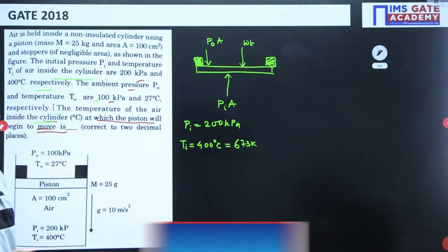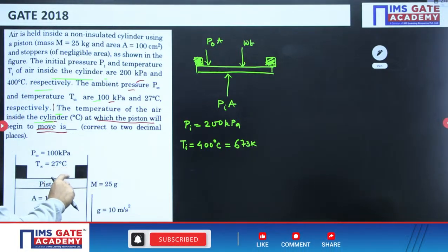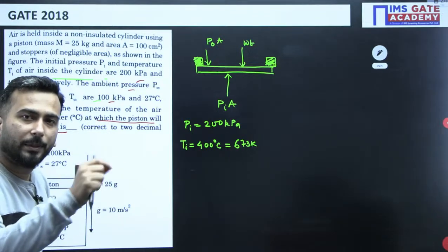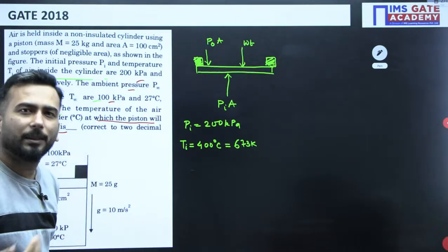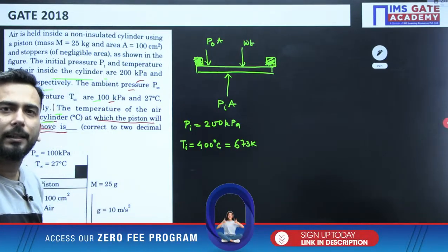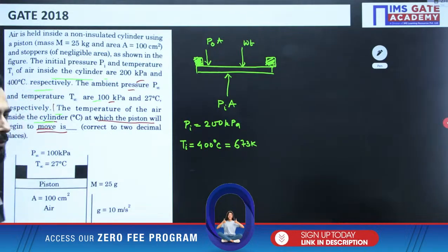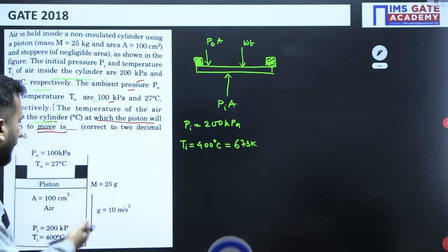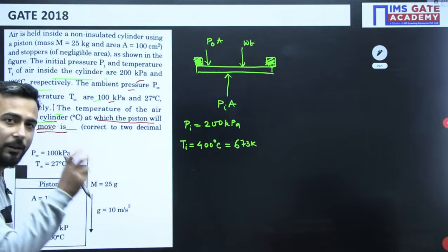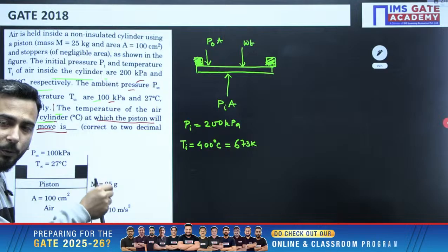Okay, now my dear friends, see one thing, now at this place how are the forces balanced right now, and how will the piston move down? When you extract some heat from there, that means if you cool, then only the piston will start coming down, yes or no? When you start extracting some heat, the gases will lose heat and contract. When the gases contract, the piston will start moving downwards.